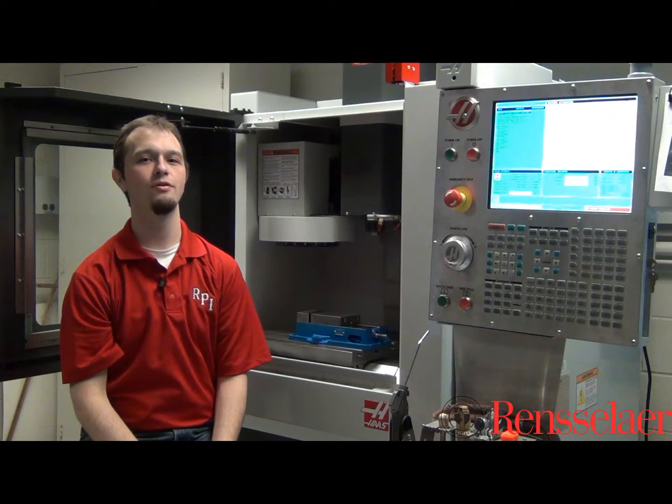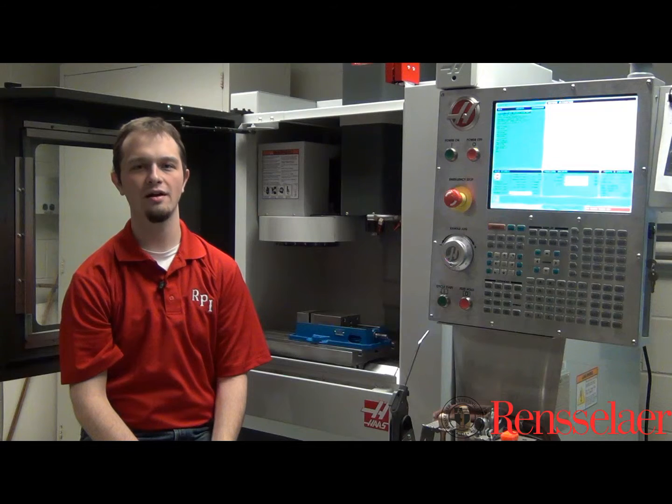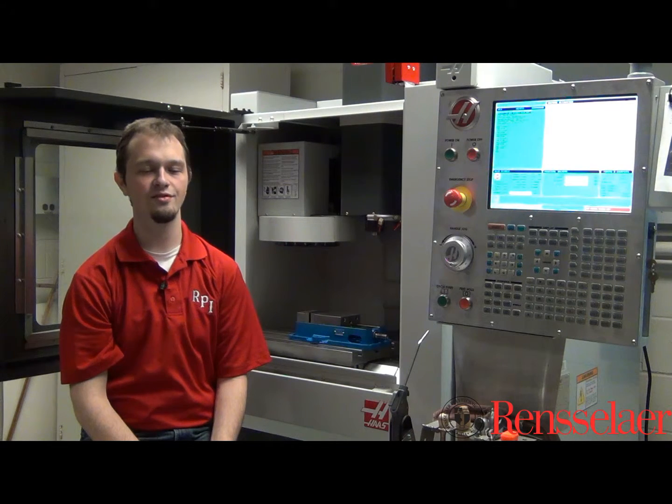First, we look at the material microstructure. At the macro scale, the material can be assumed to be homogeneous, and the bulk properties will dominate all cutting processes. However, at the micro scale, because our tool is on the same order of magnitude as the grain boundaries and the microstructure of the workpiece, we tend to see a heterogeneous structure when cutting material at the micro scale. Therefore, it's almost like we're passing through many different materials in one pass of the cut.